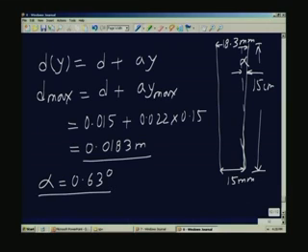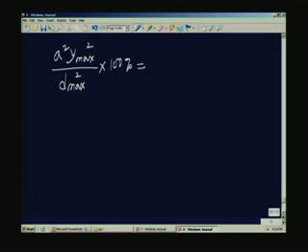And in fact, if you were to calculate including the quadratic term, so we can calculate the error in linearizing for this particular instrument, that is given by a squared y max squared divided by d max squared into 100% as a percent of the area I can find out, and this will give you about 3.23%.